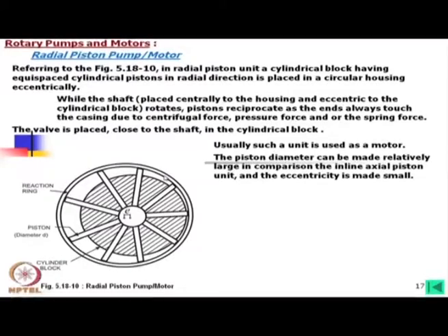So, at the most for a 100 millimeter dP we can use only 20-22 millimeter pistons. In the radial case, if the barrel size is the same, the angle is not much, say 21 degrees, a very small angle. So, reducing the space in between, we can probably use up to 25-28 millimeter pistons. Therefore, we can use very large pistons there, but eccentricity we cannot make very high. That means the stroke length will be very small.